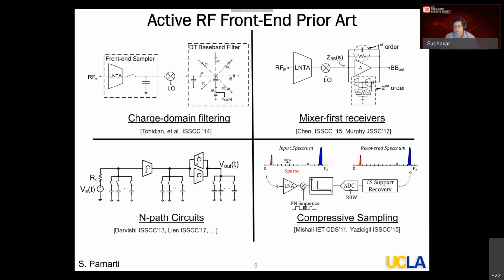So what they do is they randomize the signal using a pseudorandom sequence, and then they filter it, and then they sample it at a much lower rate. The idea being, in the sampled content, there is a tiny part of the content from all of these blocker signals, and then they use fairly sophisticated L1-based recovery algorithms, signal processing recovery algorithms, to get the signal back.